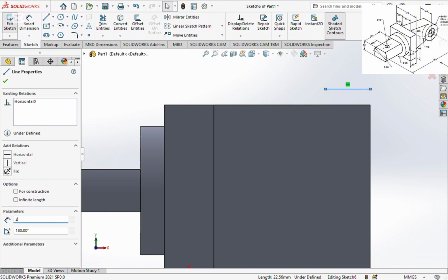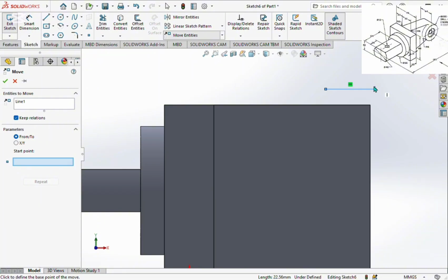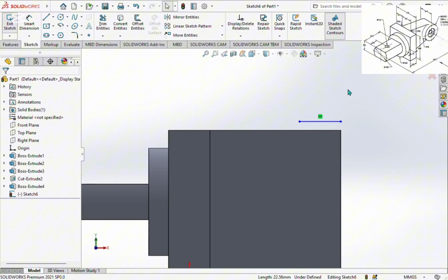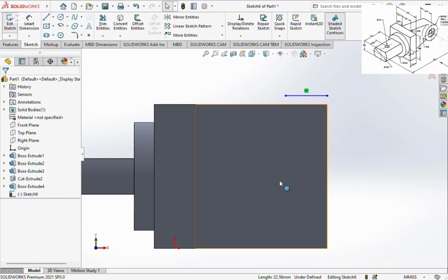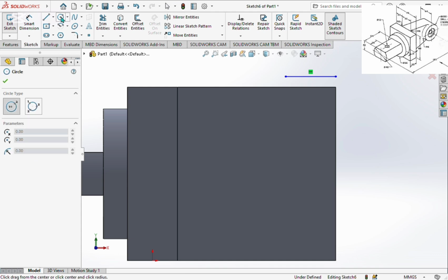the diameter of the circle is 50, R is 25. So I type 25. But you can see the line goes from the edge of the space there. So I click the line at this place, then I move it. If you just click it, holding my mouse, you can see what I have there. So just click that point, then holding my mouse to highlight it to this edge. Now, next thing now is just for me to take my circle command. It will give me my center that I need. So my circle command, when I click my circle, I will start from this point of 25 there to the center of this figure.